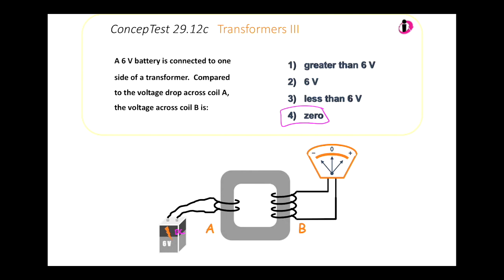Anybody? Anything? Yeah. Not about those 3, but about lower power losses. Yep. So power is V squared over R. So wouldn't a higher voltage be a higher loss? There's also I squared R, so a lower current. Yeah. There seems to be a contradiction there, right? If you work through the numbers, things should work out so that the I squared R would be a bigger loss than the V squared over R. But I'll leave you to those details.